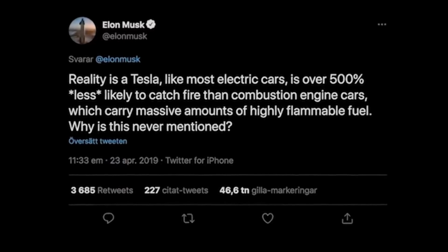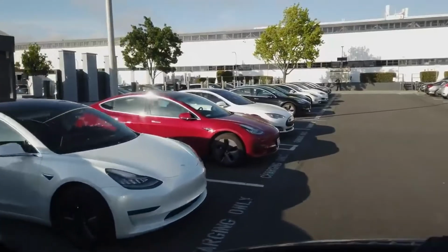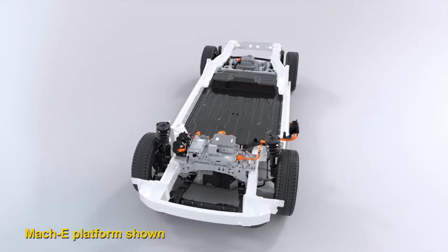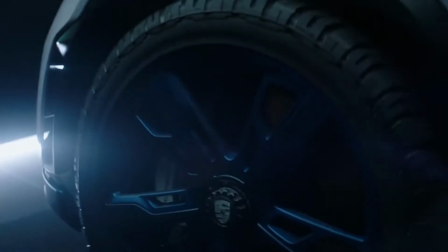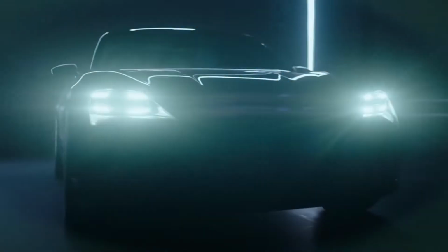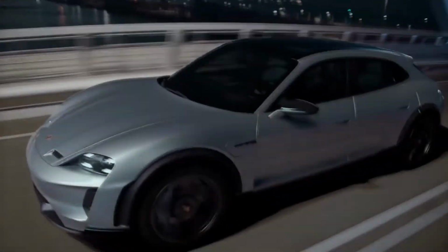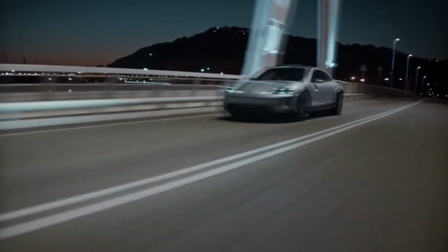Previously, I mentioned how heavy electric cars can be due to big batteries, but in most electric cars, the battery is mounted beneath the floor, which brings many advantages, especially in the safety sector. Due to the batteries being mounted below the passenger's feet, it creates a low center of gravity. A low center of gravity gives electric cars much more downforce, increasing traction on the wheels, and gives electric cars a much lower chance of tipping over during collisions than internal combustion engine cars.